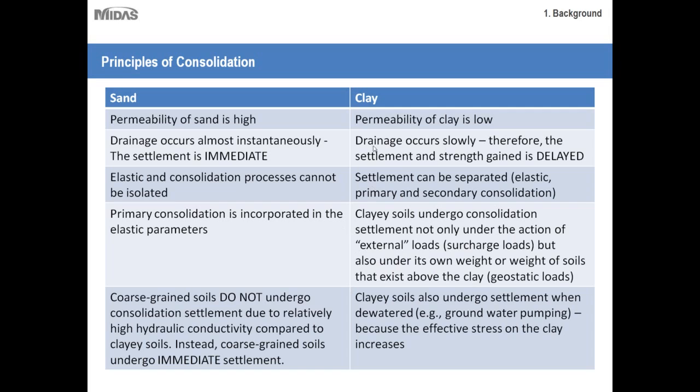Okay, so another important thing to remember about consolidation are the physical differences between sand and soil. Some important things to remember is that sand doesn't consolidate. But typically what will happen is you'll be working in project sites where the lower layers consist of clay and the top layers consist of sand. So you need to understand how the characteristics of each soil type differ and how that will affect your analysis. So the first thing to remember about sand is that the permeability of sand is very high, so water drains in and out of it very quickly, whereas the permeability of clay is very low.